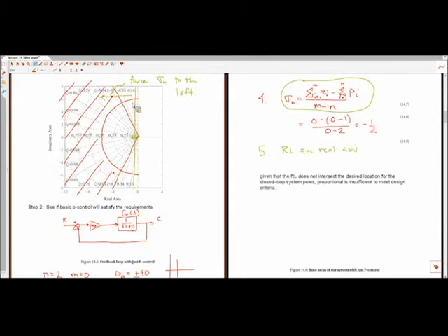So you don't try to parse this out and say, well, this looks like negative 3.3 plus 5.25i for that closed loop pole location. For this example, we're going to choose negative 4 plus 6i as our closed loop pole location. All right, so we're going to choose a closed loop pole location that we're then going to force the root locus to go through. That's the strategy here.